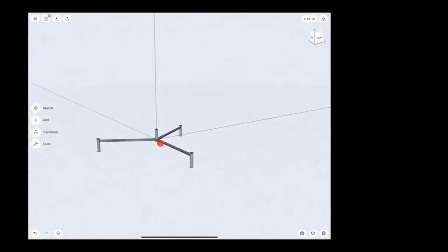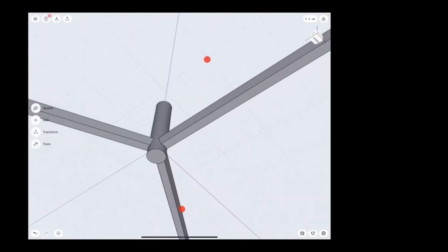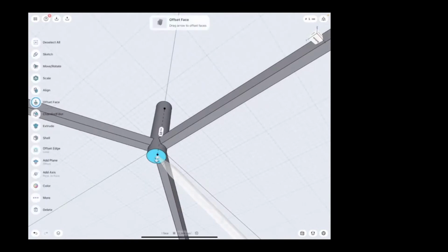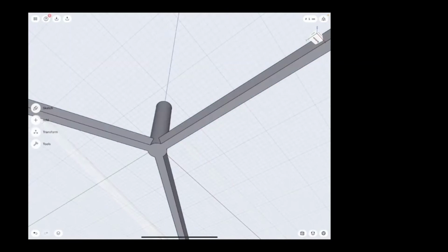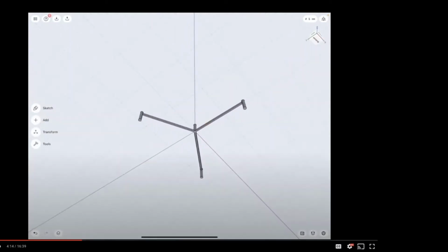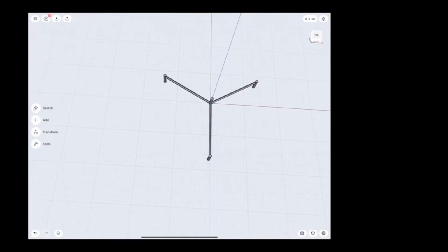And I have one single solid body with a detail that I quite don't like. That blob should be moved away. So I'm gonna select the two faces and replace the lower with the bottom of the pentagonal shape to have a clearer shape. And I have the finished channel shapes in my workspace.